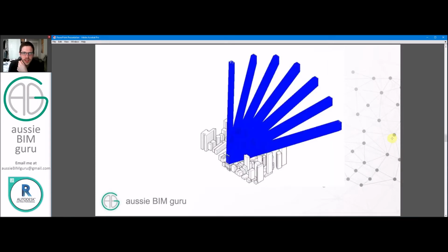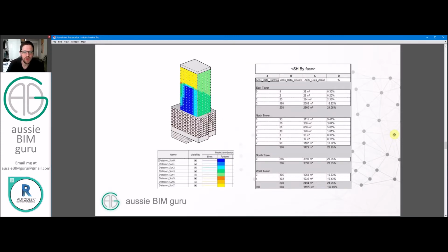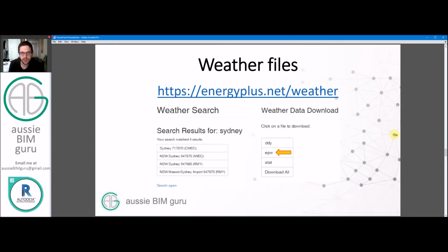We're basically going to cast a whole bunch of sun vectors from these sensors and see how many of them clash with our site. Then we're going to tally our results, and we're going to use filters to represent how many hours are being received by each sensor, to give us a rough idea of where the best locations for living space placement are in this particular mass arrangement. We can also tally the results because our sensors are going to receive data as well, so we can also schedule them, and I'll show you how to do that too.